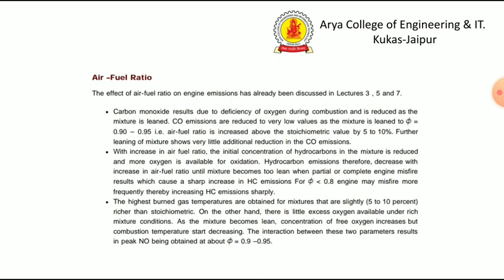The highest burn gas temperature is obtained for mixtures that are slightly richer than stoichiometric. On the other hand, there is little excess oxygen available under rich mixture conditions. As the mixture becomes lean,